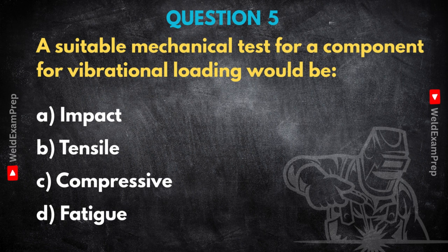Yeah, this gets into real-world service conditions. Vibrational loading means the component is seeing repeated cycles of stress over and over again. And crucially, these stresses might be quite low, well below the level that would cause it to break in a single pull, like in a tensile test. But applying even small stresses repeatedly can eventually cause failure. Through wear and tear, kind of.